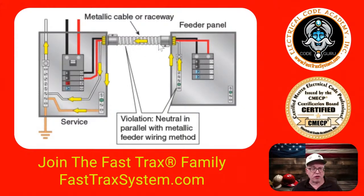Well, in this case, you could remove this and put an MC cable in there with a properly sized equipment grounding conductor based on the size of the overcurrent protective device. Although UL 1569 already sizes the equipment grounds, standardized for whatever the amps are of those conductors and whatever anticipated breaker they would be terminated to. So you really don't control that with an MC cable. Although you can order MC cable with an oversized equipment ground if you want. It's just going to be a lot of lead time and probably going to cost you more. So off the shelf MC, the equipment ground's already going to be sized for you. All right, so important. So you do have some options.